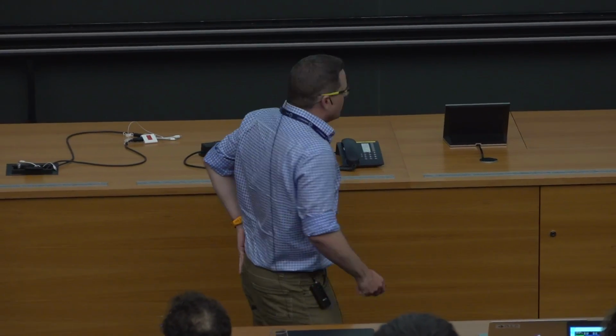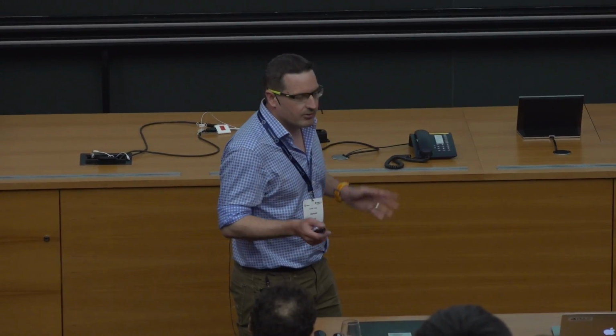So I put here, formal methods are good for processor verification. In fact, I'd say they're ideal for processor verification. Here we're talking about model checking of RTL. They're very good for finding corner cases very quickly.